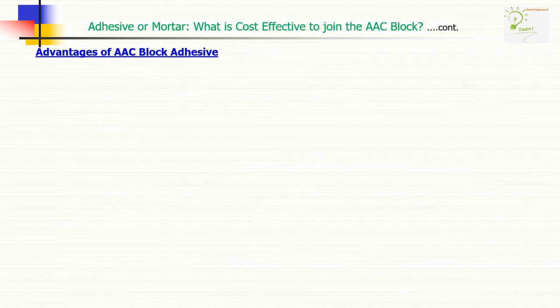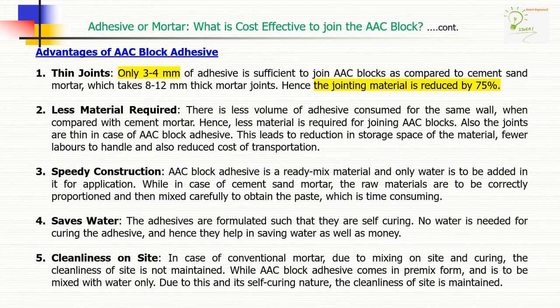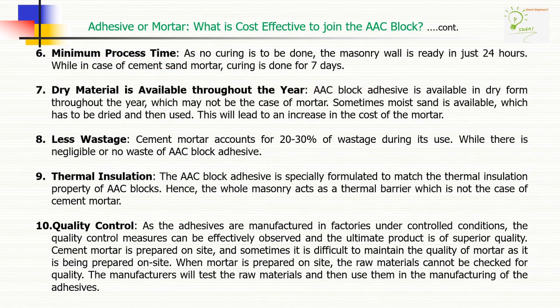Advantages of AAC block adhesive: thin joints, less material required, speedy construction, saves water, cleanliness on site, minimum process time, dry material is available throughout the year, less wastage, thermal insulation, quality control.